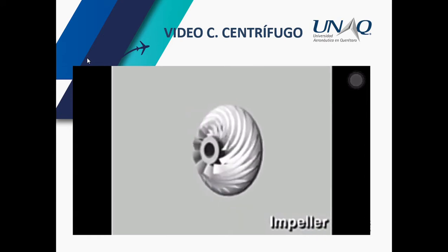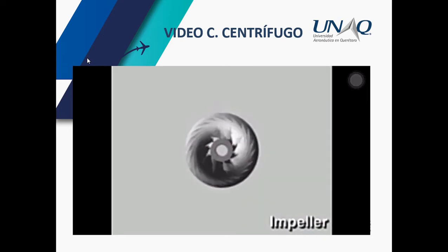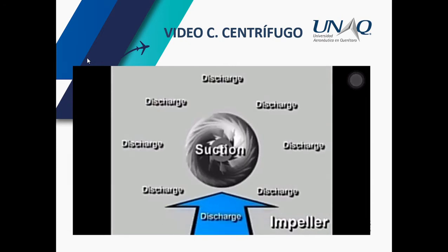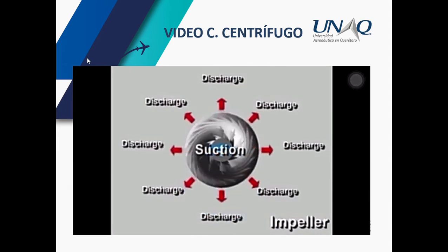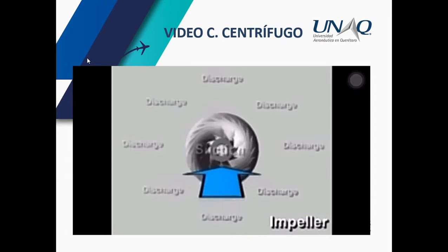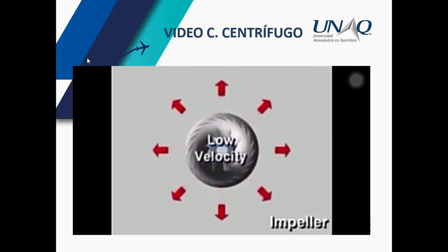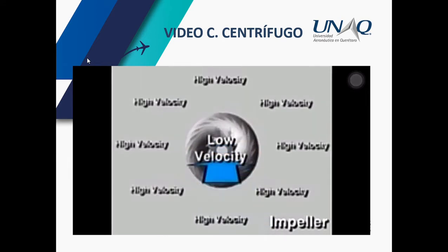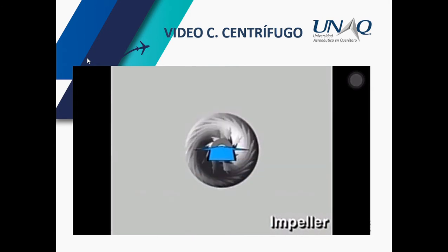The impeller is a rotating circular disc with curved blades that is driven at high speed by the electric motor. As the impeller rotates, it moves refrigerant vapor from the suction opening in its center to the outer edge using centrifugal force. The vapor enters the suction at a relatively low velocity and leaves the outer edge of the impeller at a high velocity. This means that the impeller transfers its rotational energy to the vapor, but high velocity does not relate to high static pressure.